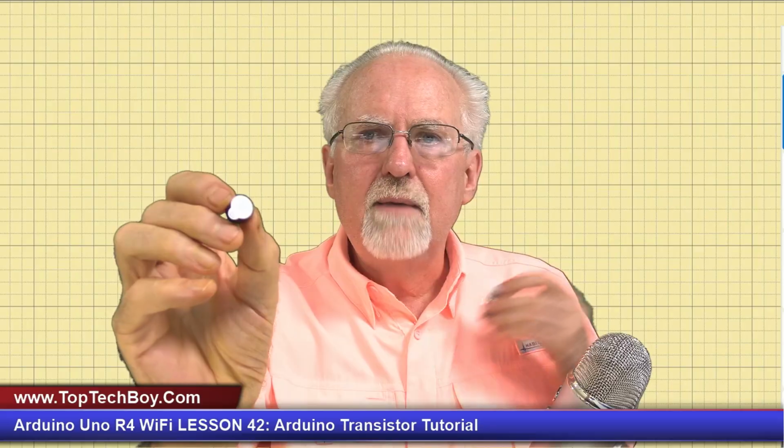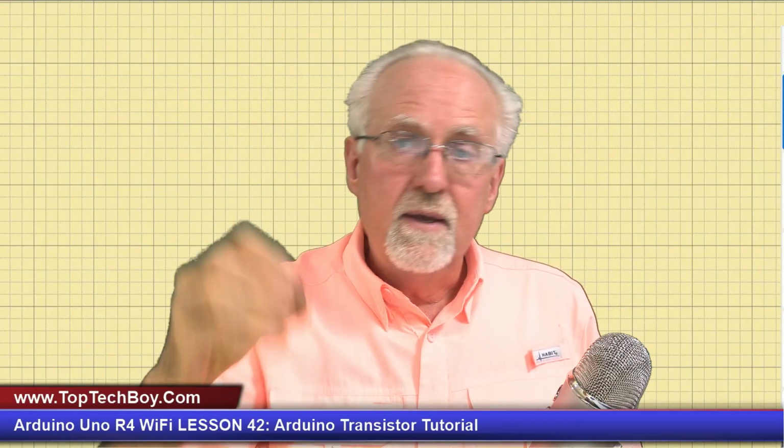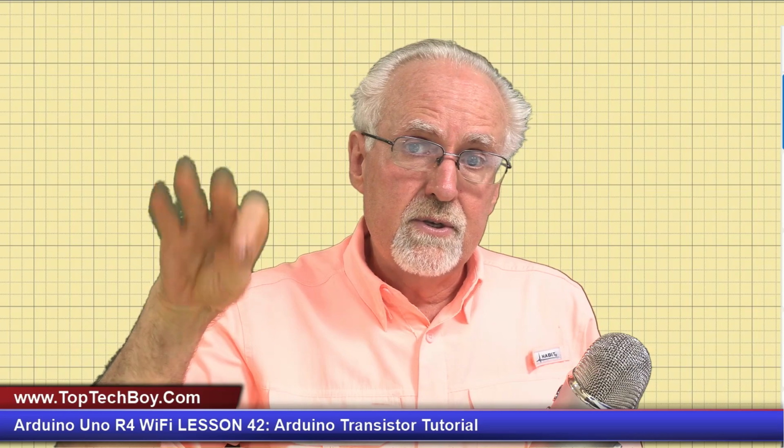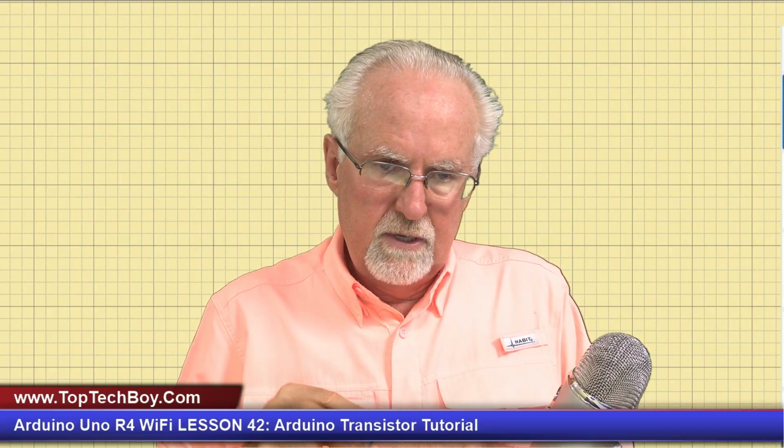Now, if your label has fallen off, you can also tell it's the right one because on the active buzzer, one leg is longer than the other leg. On that other buzzer, both legs are the same length. You want the buzzer where one leg is longer than the other one and it has the little tab on it. That is an active buzzer, and that is what we are going to be using today.